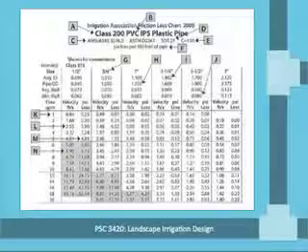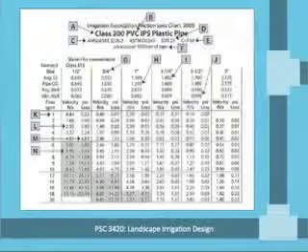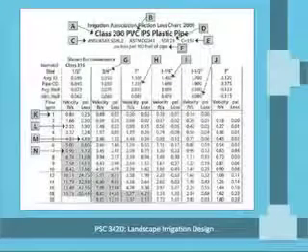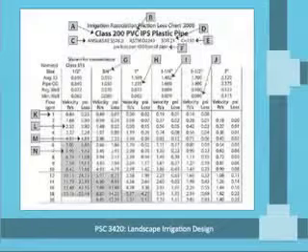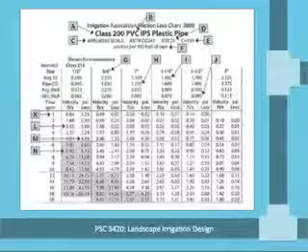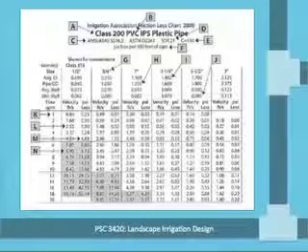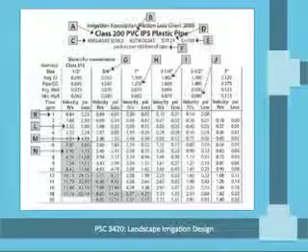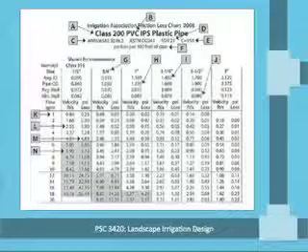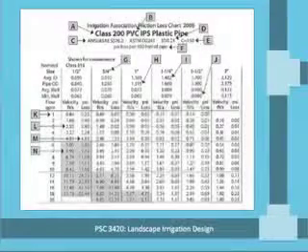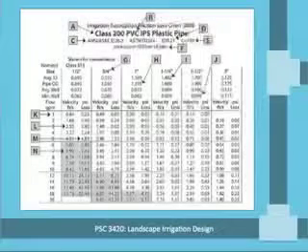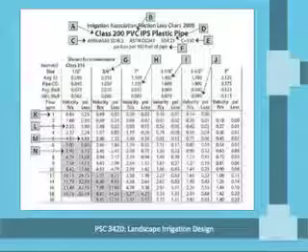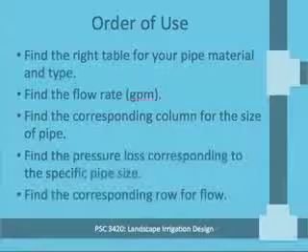That 5 feet per second is a general rule of thumb that you don't want to exceed, because it can cause problems like water hammer, particularly in main lines, and those kinds of problems can wear out pipe and other components more quickly and can even cause breaks. So that shaded area is sort of an indication of caution that you don't want to exceed that particular flow. So you might want to make another pipe choice as a result.